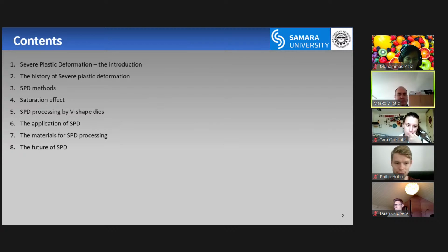After that, we're going to speak about methods. Then I'm going to mention several things that usually occur with processing by severe plastic deformation. One of them is the saturation effect. Then I'm going to talk about upsetting, or SPD processing by three-shape dies.